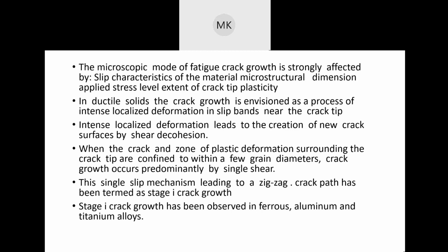So in ductile solids, you will see a lot of slip planes provided in a lot of different places, and then you will see localized deformation. So it's not that there is only one crack generated in the whole material, and that crack is the reason why failure happens. At the same time, there are thousands of cracks which are generated throughout the material. It's just that one crack becomes the major crack and how it grows towards failure. Doesn't mean that that's the only crack that happens. That's just the major crack, which was where the slip planes were.